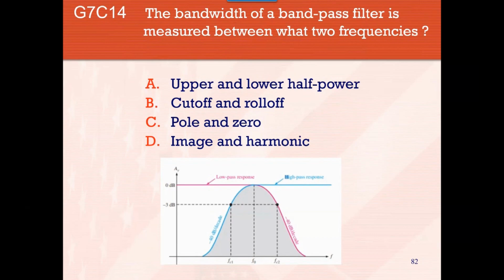That's going to allow only a certain band or a certain bandwidth to pass through that filter. And if you look at the little diagram there, see that 3 dB? 3 dB is the half power point. So as the frequency goes up and we get to the half power point, then we start to conduct, and we continue to conduct until we get to the next 3 dB point, when the high pass filter cuts off and shuts it off.